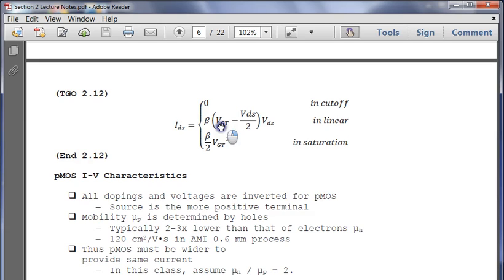So we're going to start talking more about IV characteristics. We're going to look at these graphs that have relationships between the current and the voltage for different gate source inputs, and then as the supply voltage goes up, you can see the difference. Say the supply voltage is 5, you'll get a different plot for gate source equal to 1, 2, VGS equal to 3, 4, and 5. And then we'll see the same thing for CMOS, where it actually inverts, which makes sense because they're opposite charge.